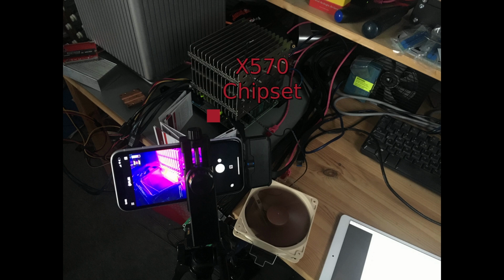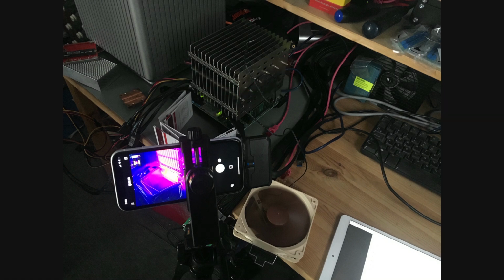We can see that I put some paper around the X570 chipset. These are actually the user manuals of the Noctua NH-P1. I use this just to shield any airflow that might be present in the room, so as not to disturb the measurement. I have a fan prepared on the side. This one is already connected and blowing air in a direction where it doesn't interfere with the measurement either. So we will use this in the course of the measurement to place it in front of the X570 chipset and then observe what is going to happen.